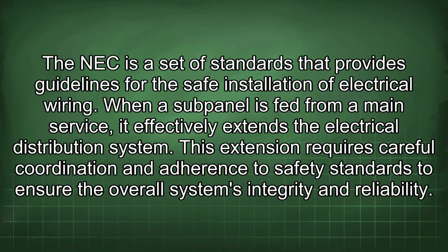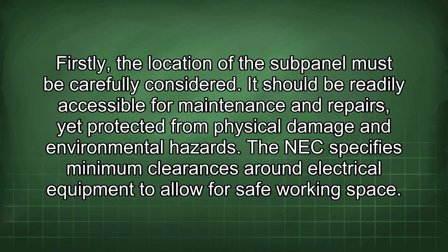When a subpanel is fed from a mains service, it effectively extends the electrical distribution system. This extension requires careful coordination and adherence to safety standards to ensure the overall system's integrity and reliability. Firstly, the location of the subpanel must be carefully considered. It should be readily accessible for maintenance and repairs, yet protected from physical damage and environmental hazards. The NEC specifies minimum clearances around electrical equipment to allow for safe working space.